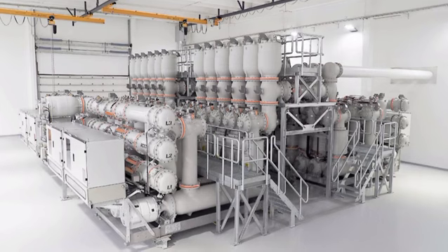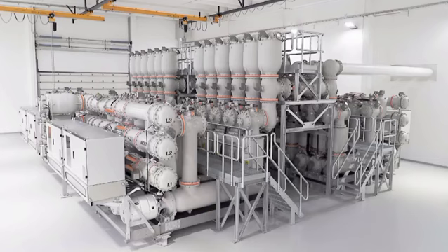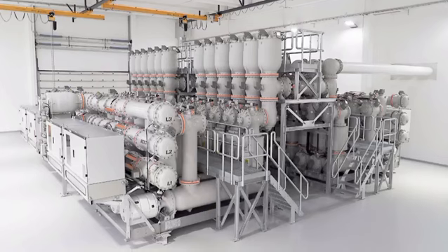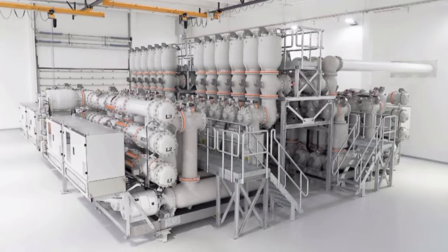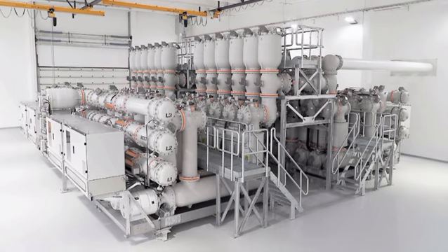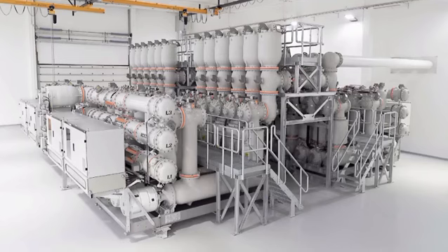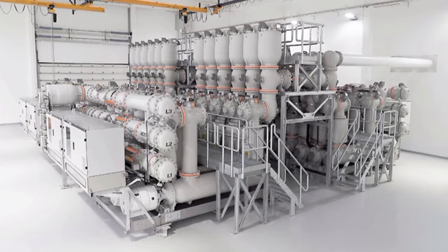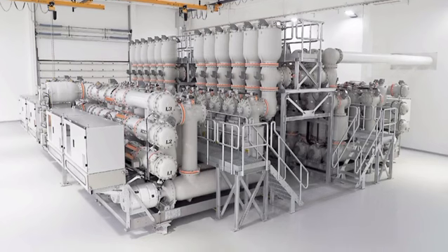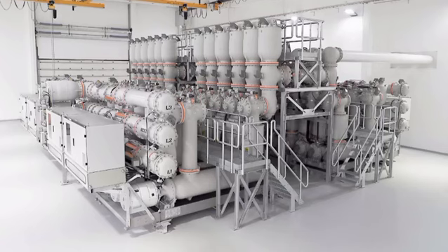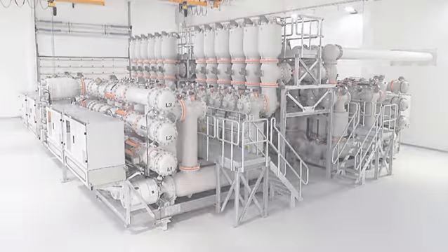using sulfur hexafluoride (SF6) gas. This design reduces the size of the substation and makes it suitable for urban and high-density areas where space is limited. Advantages: compact design, reduced footprint, and minimal environmental impact. Disadvantages: higher initial cost and more complex maintenance due to gas-insulated equipment.